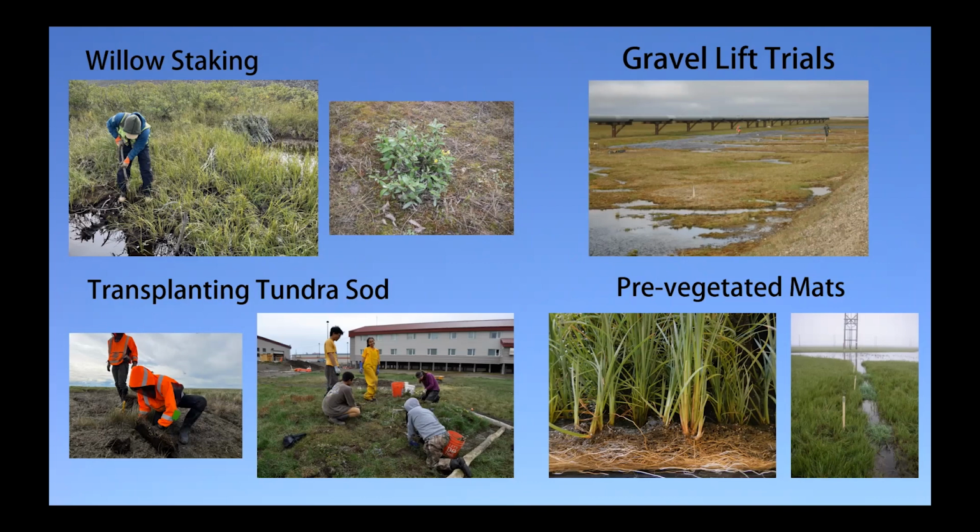She collected seed, took it back to her lab in Minnesota, and grew these mats, and in the bottom picture here, you can see the roots that grow when you grow them just in a peat medium. And so these mats you can just pick up because the roots will hold them together. And then I installed them, and we're going to visit that site today where they were installed. I'm actually really excited to see how they look today. And this is both a water management technique and also creating a thermal blanket and immediate vegetation.